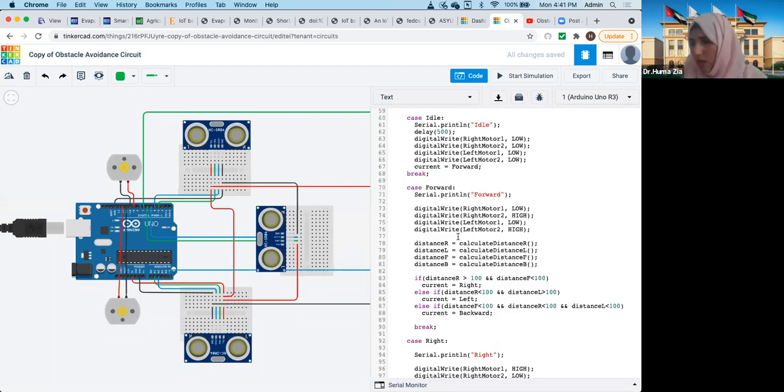This is the main loop and different states that I showed you in the FSM that are being implemented. In every state, you are setting up the direction of the motor, because if you recall, this is what we did in the FSM. In whichever state you are in, both the motors are set to go in a particular direction. In the forward direction, both the DC motors will be going forward. Whereas in the backward direction, both the motors will be going in reverse. And similarly, right and left, I told you how it's made.